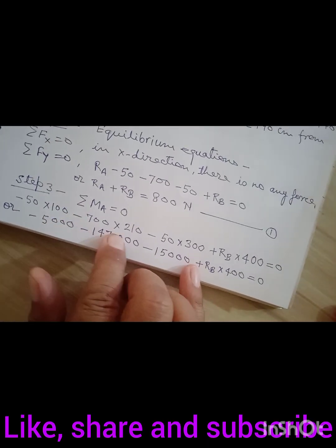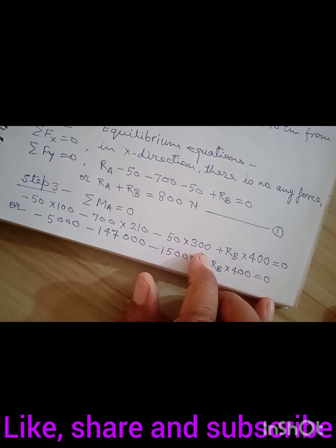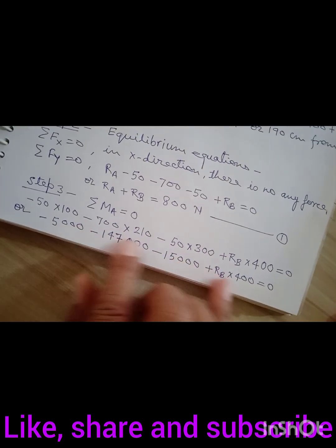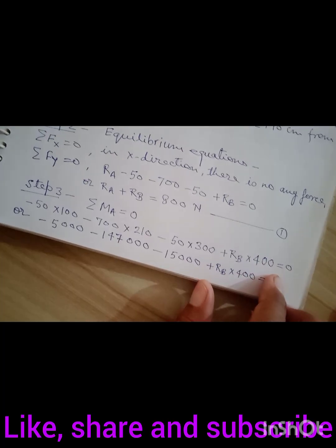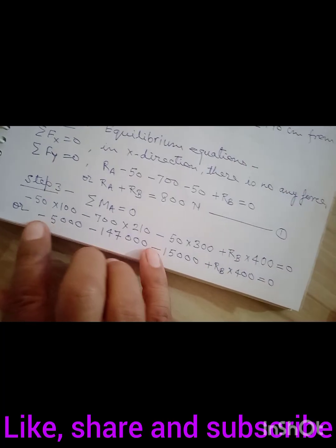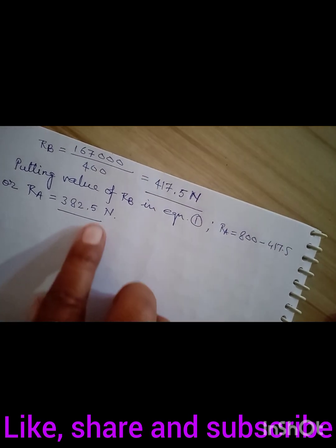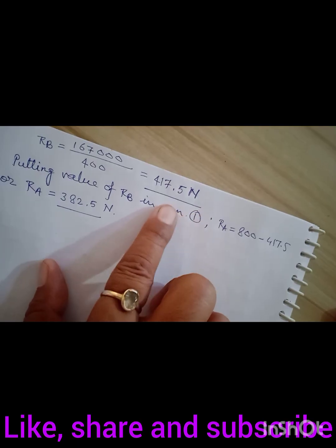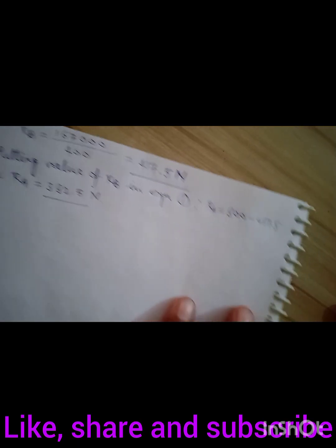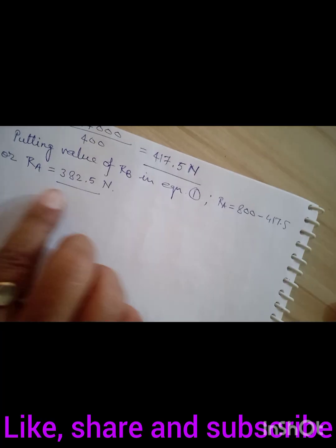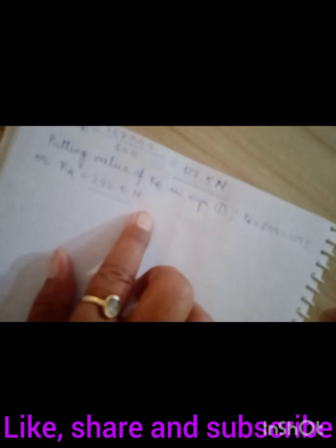Minus 50 into 100 centimeter, minus 700 into 210, minus 50 into 300 plus RB into 400 is equal to 0, as RB has a perpendicular distance of 400 centimeter from point A. Solving this equation we get RB is equal to 417.5 Newton, and putting this value in equation 1 we get RA equal to 800 minus RB, so RA is equal to 382.5 Newton.